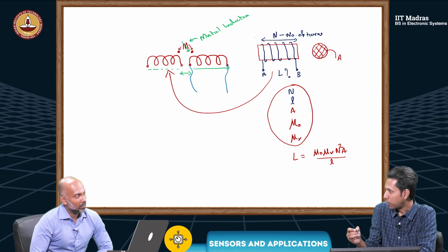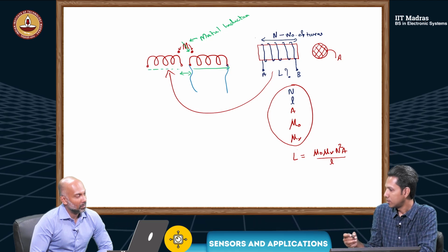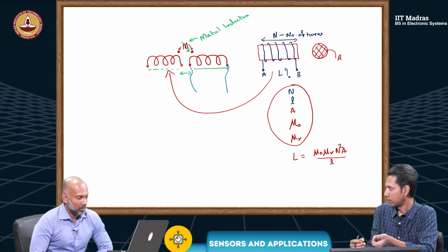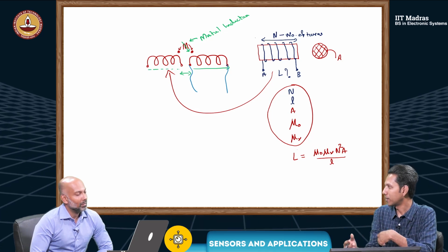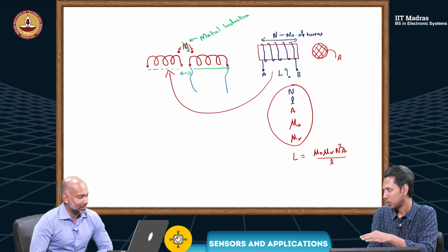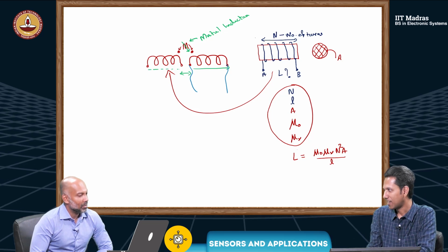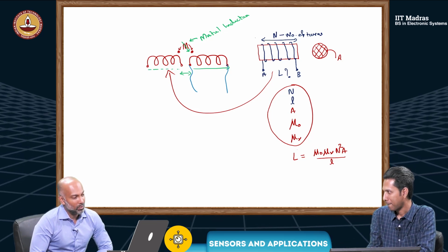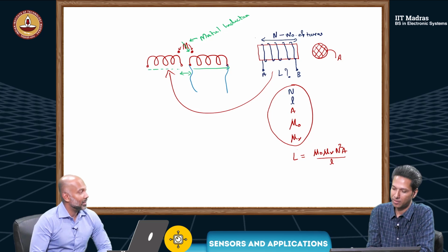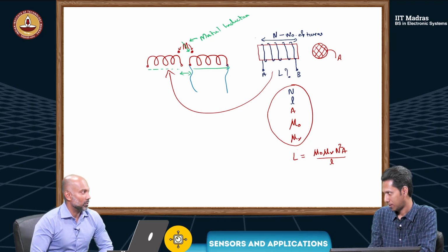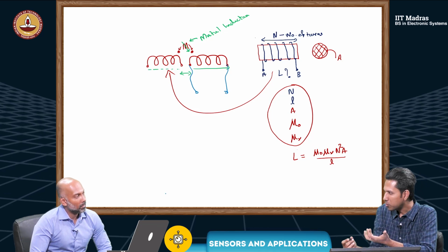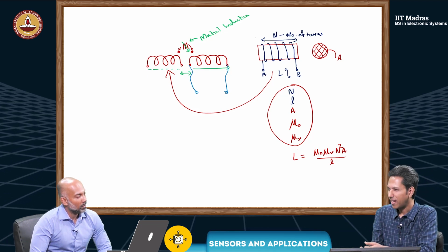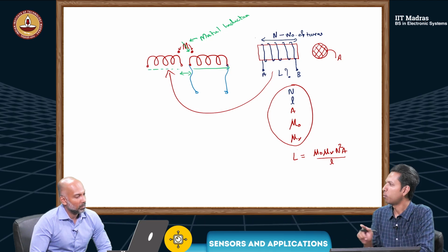When I move the plunger, these wires will also be moving. That's true. Of course, how many times can you bend these wires? Right, so the lifespan will be affected, especially if you're using it in an industrial setting. Correct. It will just break after a few rounds. So that will be a problem. Preferably, I would avoid any wire connection from a moving part.